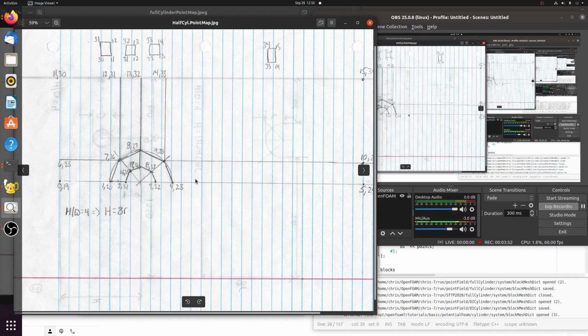It's cut off, but you can make it more custom, and you can use the same settings: symmetry for the upper wall, symmetry for the bottom wall, and I'm using a no slip wall condition for the cylinder. Some people use symmetry for the circular cylinder, and I'm just using no slip. I saw that in another person's development, and I don't know if symmetry does the same thing. I'm not 100% sure about what symmetry does.